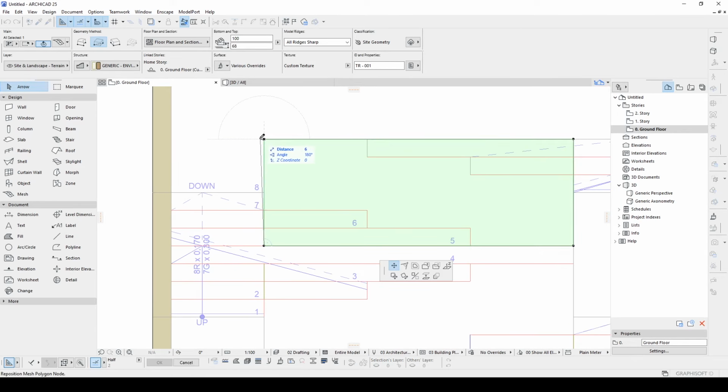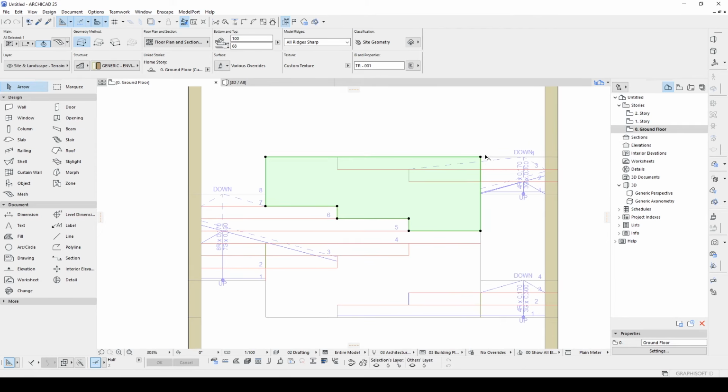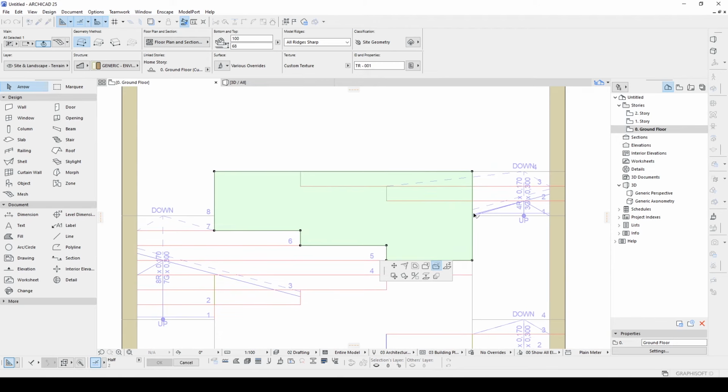Let's click any edge or point and click this minus subtract from polygon and change the drafting method with this polygonal. And subtract the unwanted edges, unwanted stair bars, like so.